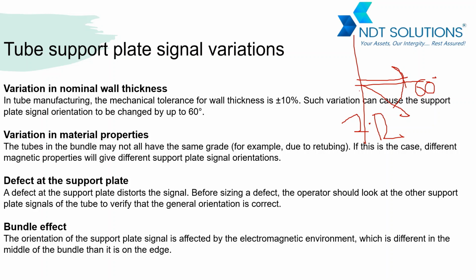Apart from that, if there is a defect under the support plate or nearby the support plate, that may also change the angle of the support plate. And another thing is the bundle effect. Have you heard about this one, the bundle effect? Bundle effect is just the effect of nearby tubes while doing the inspection.